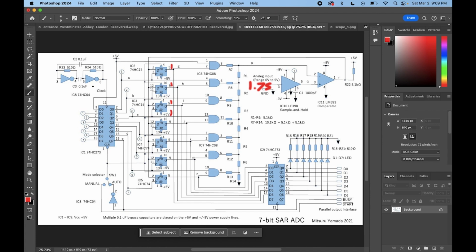So on the first cycle, what we do is we set this AND gate high because we have a 1 here and we have a 1 from 5 volts. So we have a 1 and a 1. That results in 1 here, which results in 2.5 volts here on this comparator, which will generate a high here.